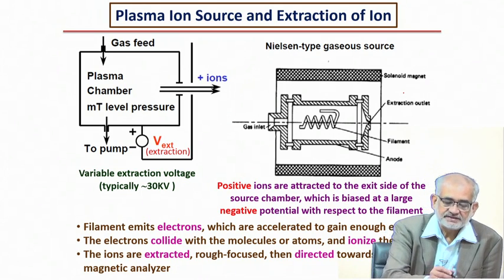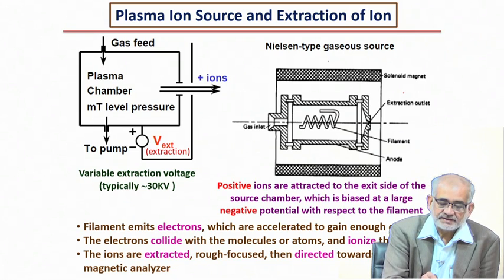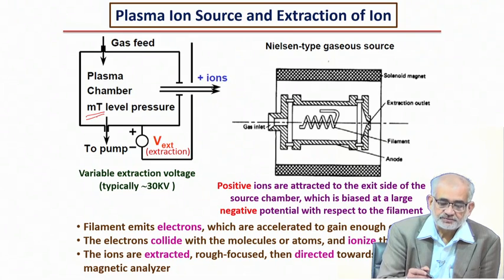In fact, if you remember, I said that typically if you're treating some semiconductors, say silicon wafer, and you would like to implant phosphorus, arsenic or boron, you'll be starting with a very highly volatile gas like phosphine or arsine or diborane, and then allow them to come to the vapor state, and then fill a chamber at a very low pressure, millibar or millitorr pressure, and then use a certain electrical discharge process to create plasma.